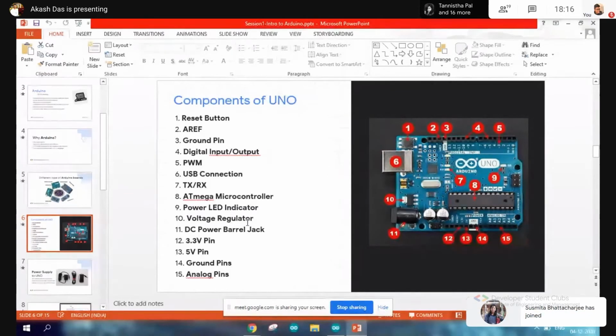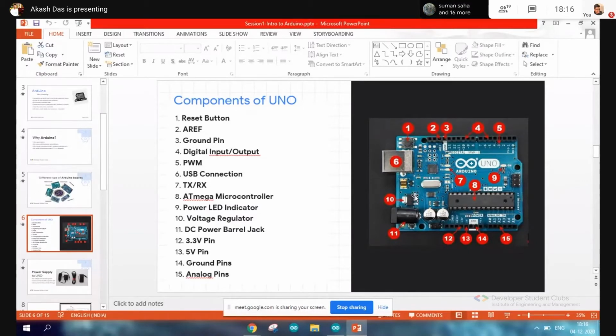Arduino has a 5-volt voltage regulator to convert all the noise or all the voltages that are coming in to 5 volt, so that it does not destroy the board. For electronics, it is very important to control the voltage and the current, because an increase of just a few millivolts or milliamperes can damage the whole board. Yes, and it has happened with me a number of times, and it's really frustrating. So before giving power, we need to regulate the voltage to the exact voltage required by the board.